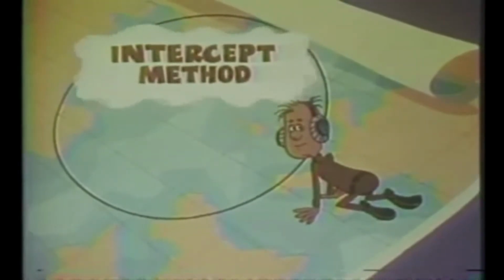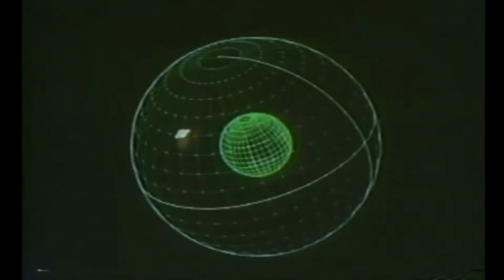As with the first method, it may begin with an observation with the sextant to determine the sighted altitude, or HS, of a celestial body above the horizon, and a notation of the date and Greenwich Mean Time of the observation. This observation enables you to determine corrected observed altitude, or HO, an important factor you will use in a few moments. Now you begin computations by finding the geographic position of the observed celestial body. This means determining its GHA and declination on the celestial sphere. Then, translating those coordinates to latitude and longitude on Earth.